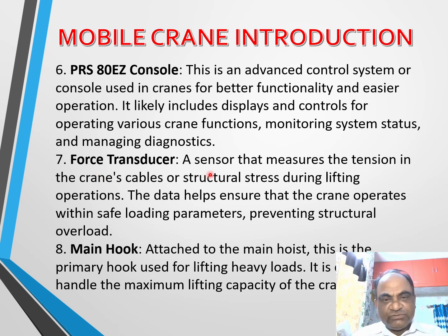The force transducer, a sensor that measures the tension in the crane's cable and structural stress during the lifting operations. The data helps to ensure that the crane operator stays within the safe loading parameters and prevents a structural overload. So this is very, very important from the lifting point of view because lifting higher than the capacity of the crane could be dangerous.